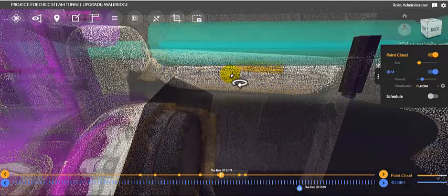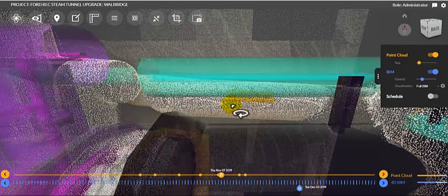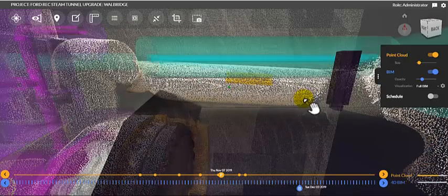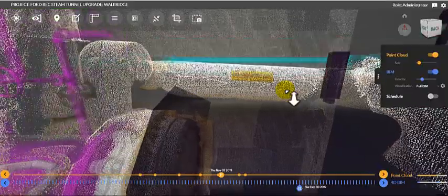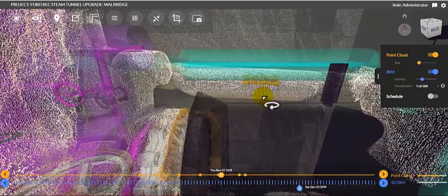And this alignment could either be by maybe we need to register the targets, or in fact it was modeled at a theoretical elevation and the actual elevation looks angled or pitched. So that would require a little bit more investigation. But you can do quality checking like that.